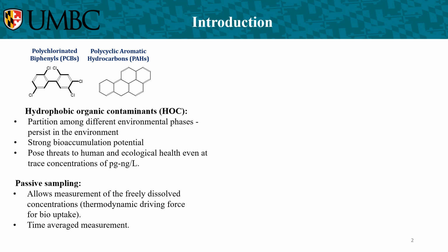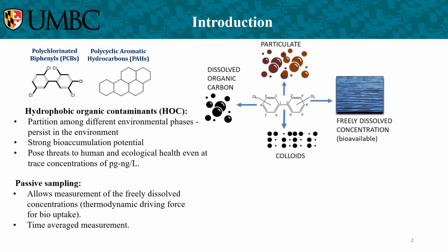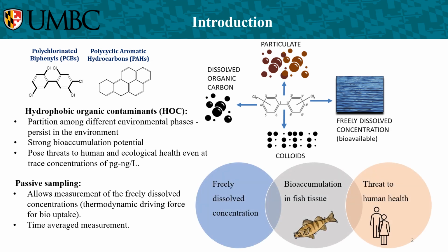Hydrophobic organic contaminants like PCBs and PAHs have strong bioaccumulation potential and persist in the environment long after their use has been discontinued. They keep partitioning among the different environmental phases. Using passive sampling, we are able to measure the freely dissolved concentrations of these HOCs, which is the thermodynamic driving force for their biouptake. Passive samplers also provide a time-integrated measurement of the concentration levels at a site, which is important for ecological exposure assessment.